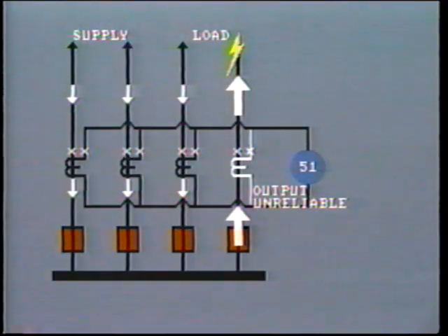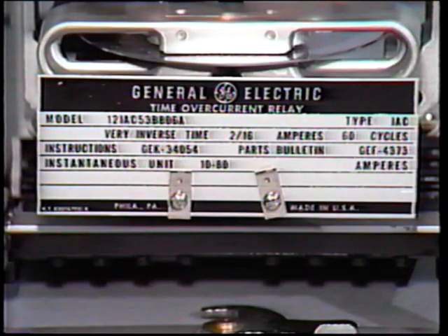So now we have two factors resulting from saturation. A, the non-increase in secondary current as the primary exceeds the saturation point, usually about 20 times rated, and B, the reduction and distortion of secondary current due to the declining DC component of the transient fault current. All this means that for the first few cycles after initiation of the fault, the output of the heavily loaded CT will be most unreliable and will probably cause false tripping. As we shall see, there are several ways to get around this problem.